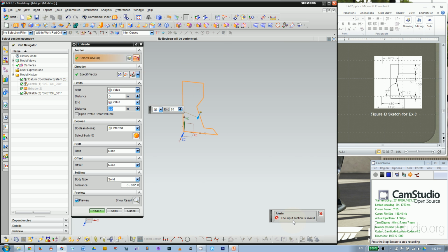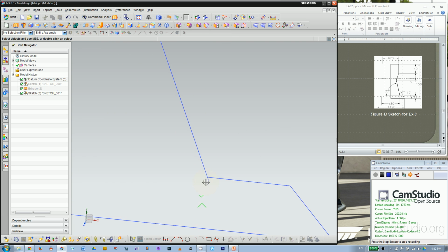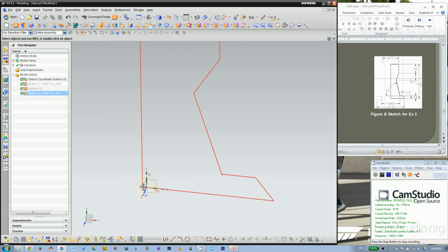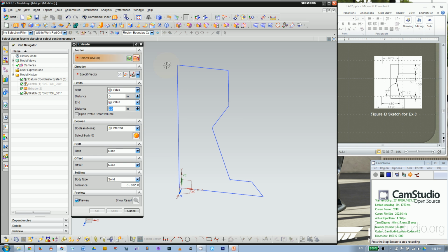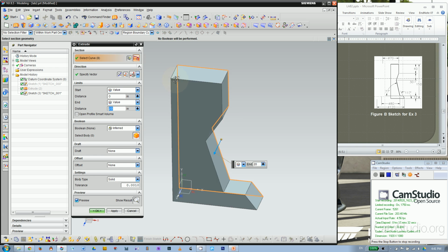Okay, that will give you an invalid because of this sticking out. So the sticking out, the gap, overlapping, that's all very terrible, poor quality sketch. Okay. Of course, you can get away from it, I think, with this option, region boundary curve.